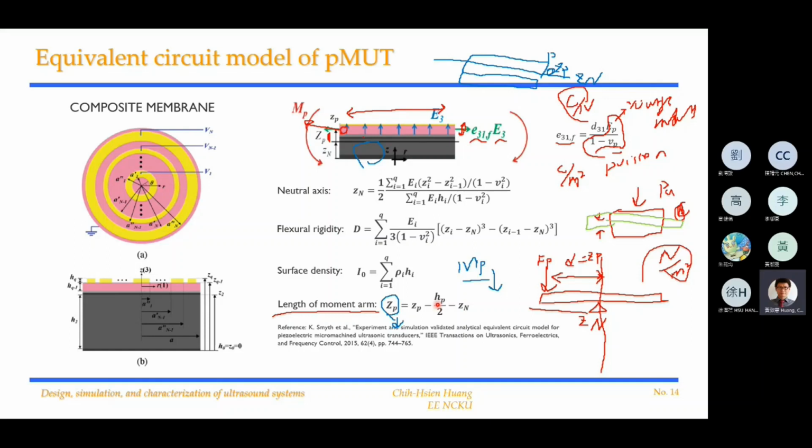Because the larger the thickness, the larger the charge, which usually can create more deformation. And if we use thicker supporting layers, it makes the entire structure thicker, and if we want to maintain the same frequency, we have to increase the dimension of the entire device.